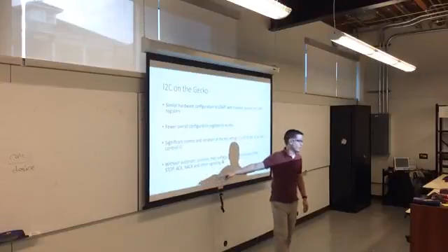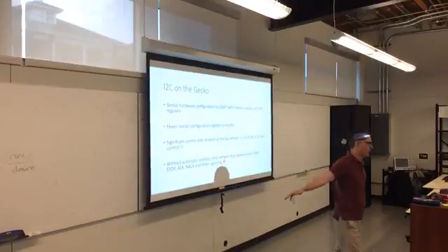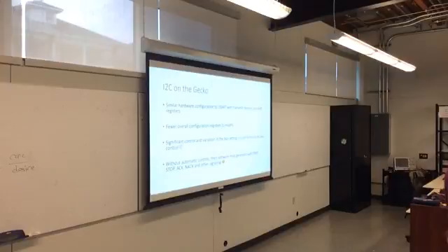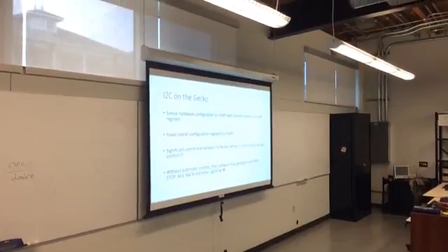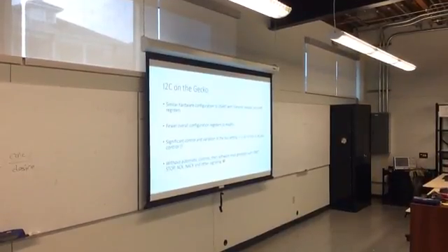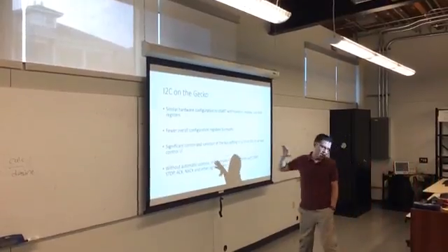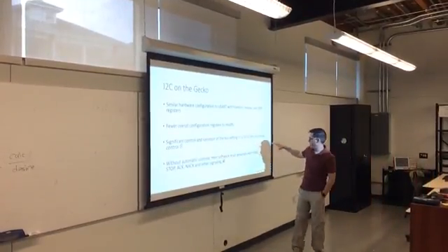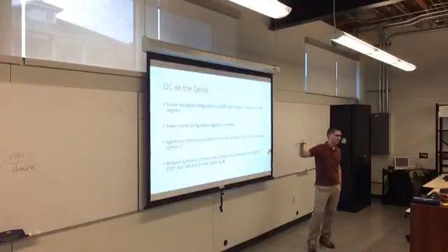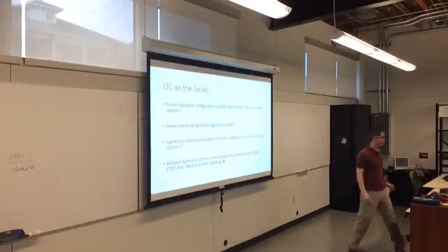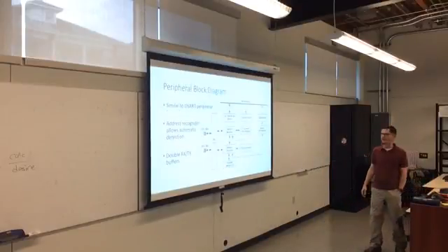of this signaling yourself. So, if you were to get an Arduino and hook something up over I2C, it makes it look nice and simple with all the start bits, stop bits, NACKs, ACKs, all that stuff, because it hides it from you. And it's actually a blessing that it does because it's annoying. But here on the Gecko, you have to generate all of these bits on your own. There are certain registers that you're going to use, but you have to create all of those bits.